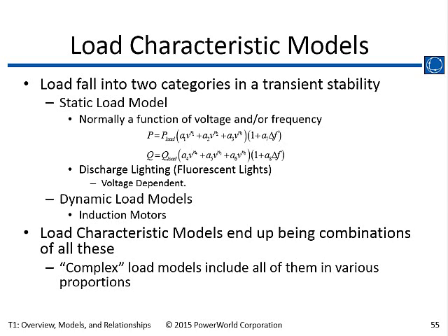Okay, but there are some slow modes that we'll talk about later on. You do eigenvalue analysis on a single machine infinite bus, you see positive eigenvalues, which, if you took a controls class, are growing with time. They exist. It's not necessarily even a model error. Well, I don't think they exist in the real grid, but they exist in the model. So I would call it a model error.